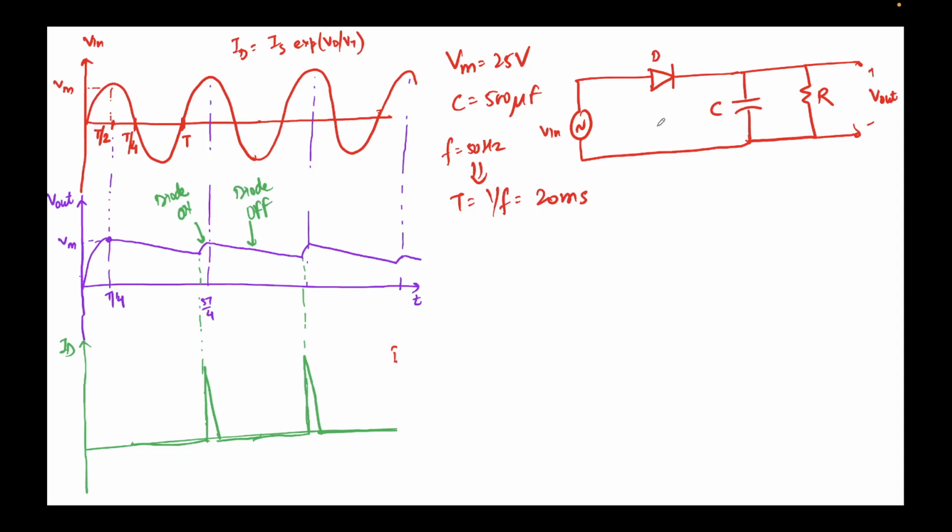Now just look carefully. At this junction, when the discharge cycle has just ended, this capacitor is most discharged, right? And the difference between the voltages would be highest, because as soon as we enter the charging cycle, this voltage will continue to rise. So we expect that the current through the diode might start to drop, but we'll have to evaluate whether it indeed drops or not. This is just for the feel.